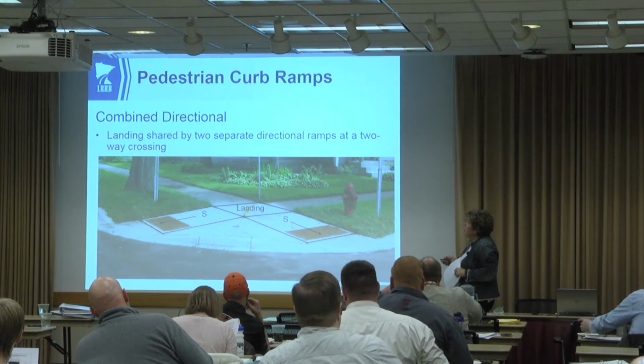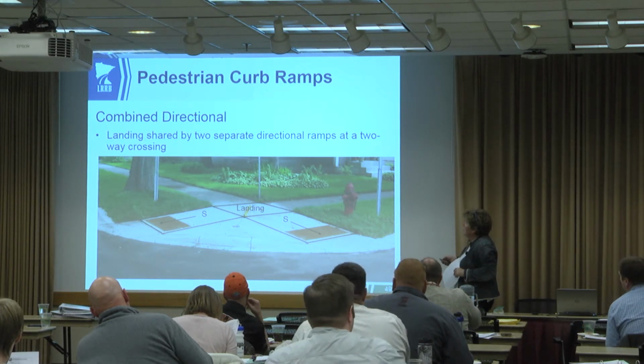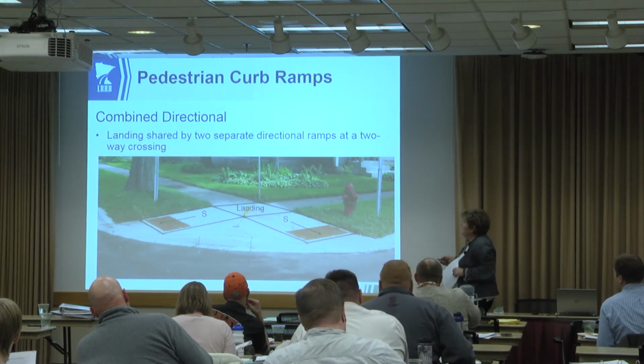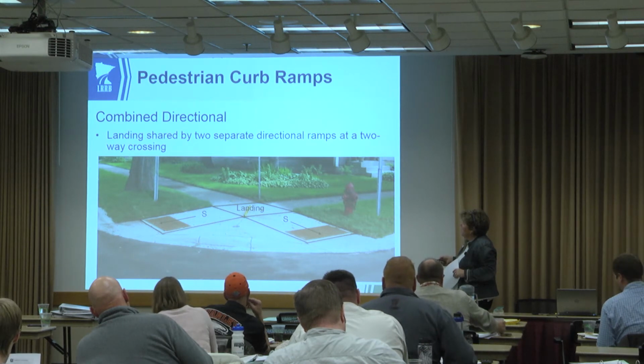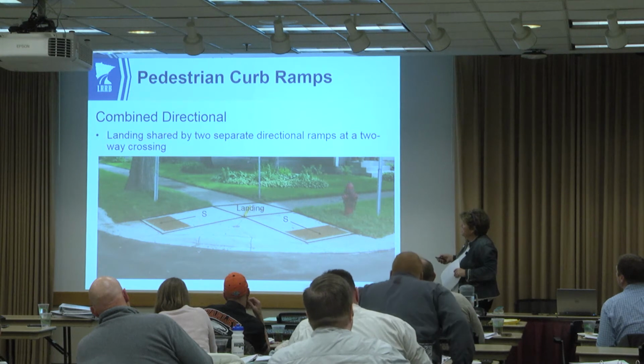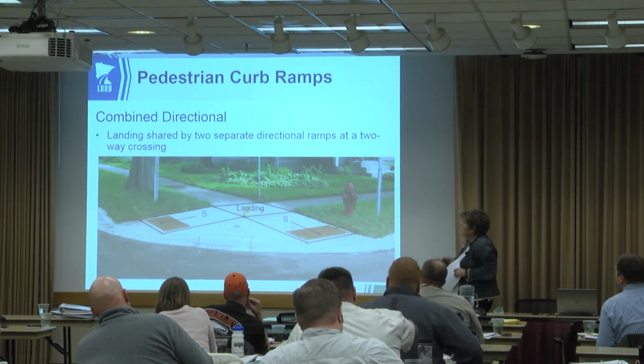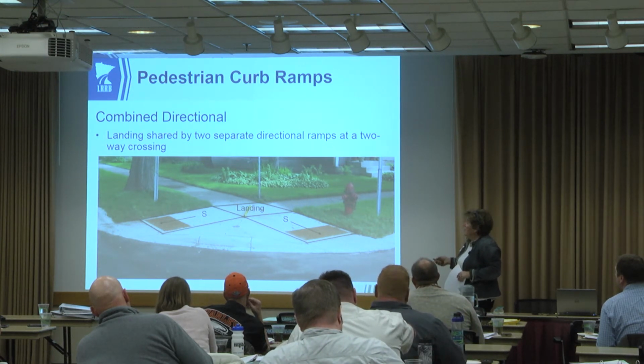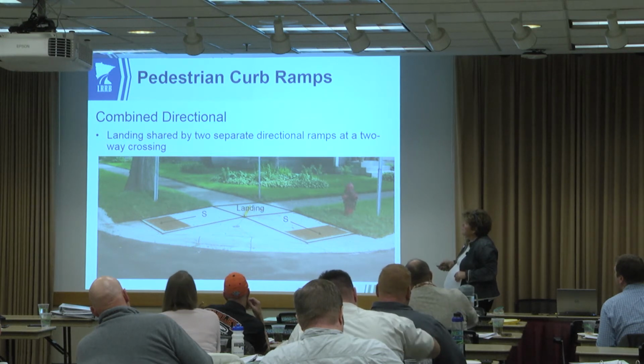Here's where we show one landing shared by 2 different sidewalks. The landing up here is used for 2 purposes: to accomplish a change in direction for this user here, or to accommodate the fact that this is a steep slope.